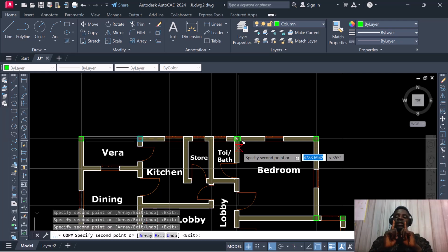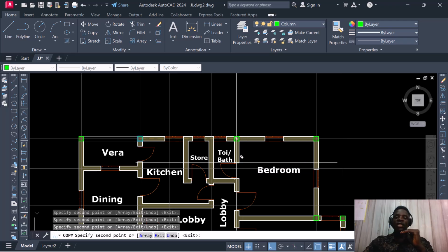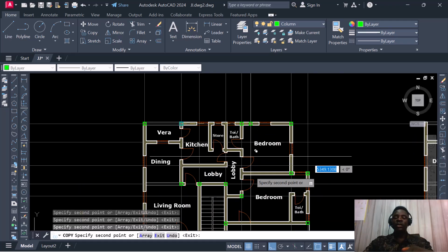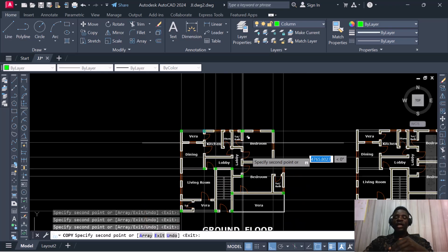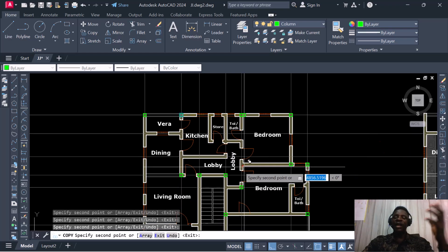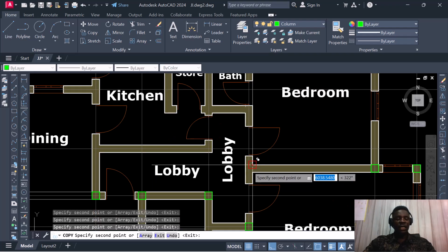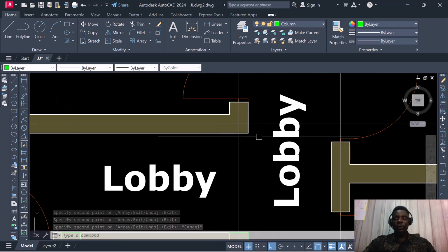So we want to keep it as safe as possible. So we don't want to jump to get up to 10 meter also. So we want to keep a range of 5 meter, so that we'll be having a moderate detail, because every detailing you're performing here, the support you're creating, all you're modeling over here is how your analysis is going to come out. So you're going to have a higher reinforcement. So we don't want to have a higher reinforcement on our beam. All right, so we want to keep it simple by adding a lot of support